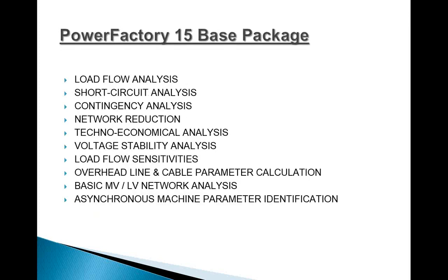Now we will talk about what the base package includes. We can do load flow analysis, short circuit, contingency, and network reduction tools are there, and also techno-economical analysis, the analysis related to economical expansion and the strategies which we lay out while planning the power sections. That kind of assessment we do in techno-economical analysis.